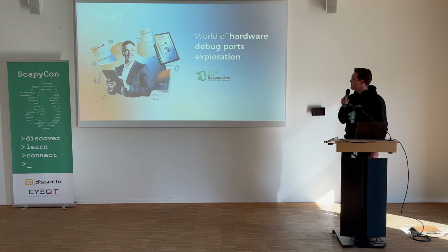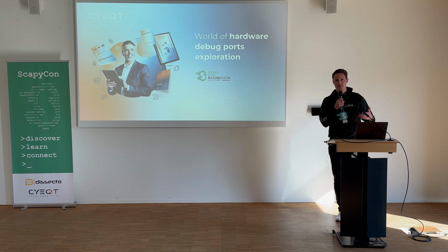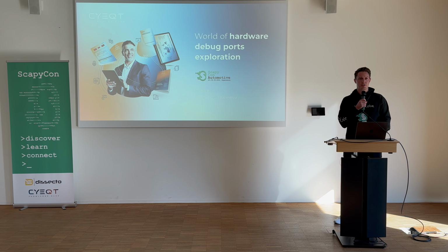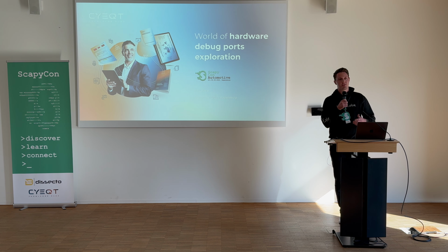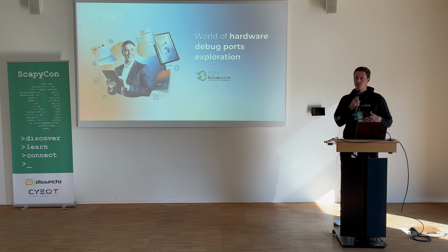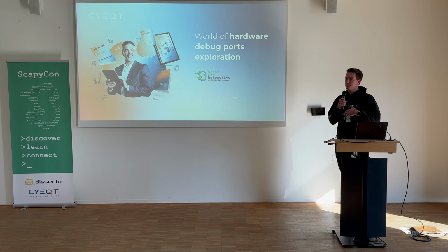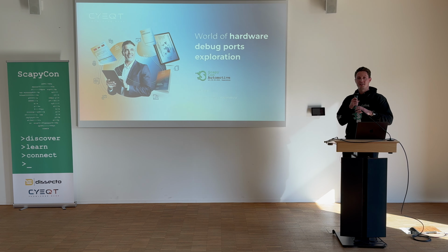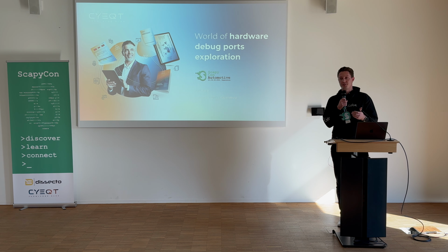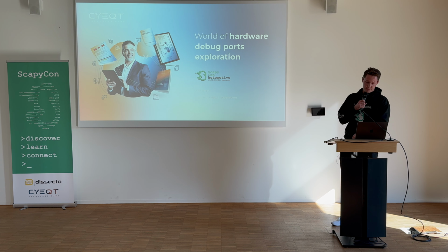I want to introduce you to how you connect to a JTAG port on an automotive unit, or in general to a JTAG port, especially without very expensive debugging equipment. As you're probably aware, when you go into sourcing offers from vendors, for example iSystems or Lauterbach, they are somewhere in the tens of thousands, and you have to purchase one for every different architecture you are looking at. This is why we're going to look at this today.